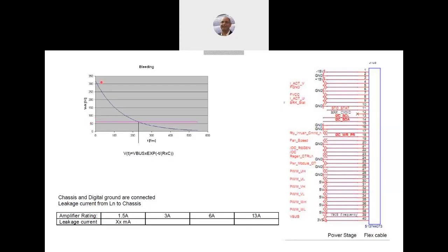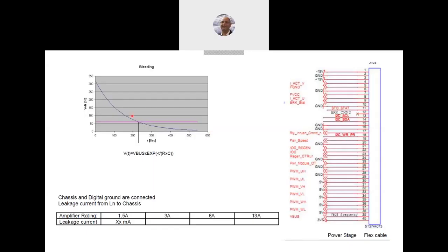So this is an Excel spreadsheet I did from a real, this was a CD many years ago, where I took... Okay, I mute all. And if you look here, it takes about 220 seconds to discharge the capacitor. And that's the reason that you will always see on the label of a servo drive, wait 5 minutes. If you look at some European ones, it tells you that it can kill somebody. So that's the time to discharge the capacitor.